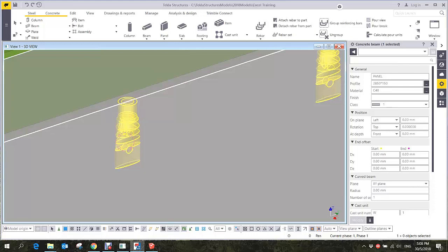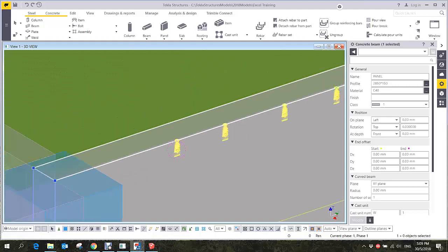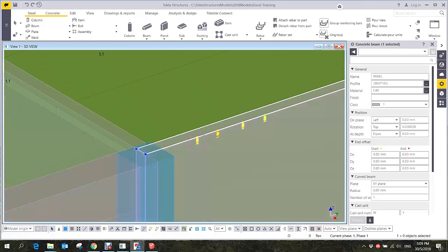So is the bar part of this, or is it under rebar? If you're taking out the quantity, it depends what you want. Because for PVC we are using the I angle, and we also put the bar, and the bar is quite heavy actually. Is your bar a rebar or just a rod? In terms of rebar usage, we want to treat that one as a rebar. As a rebar, it will go to the bar bending schedule.